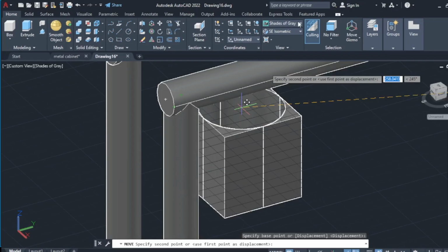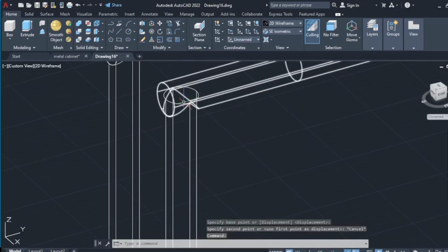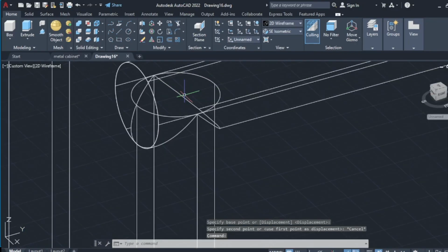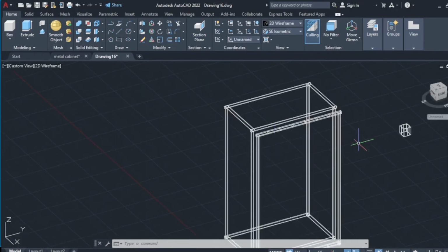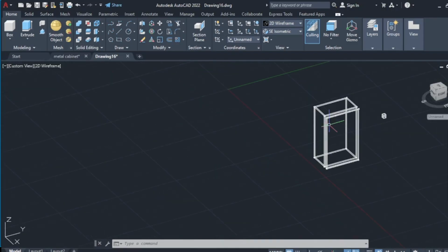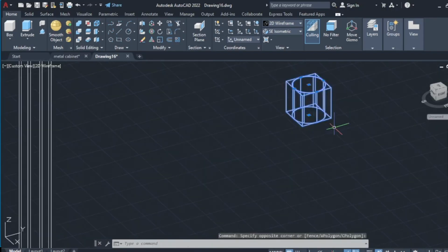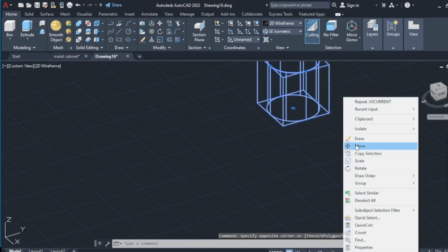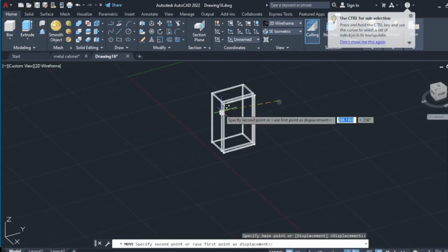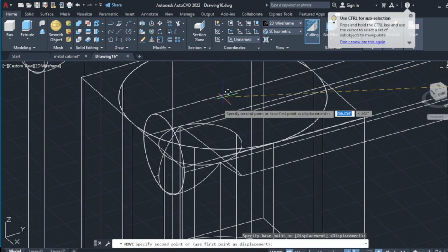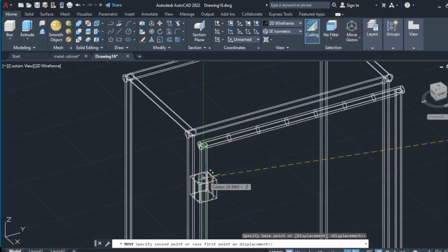So you guys can understand what I'm trying to do, we made a new circle here so that we can find the center of this rod, so we can drag this hinge to the center. That's exactly what I did. You highlight this, you copy or you move, you pick the center here, and you come here, you find the center here, then you just drag without doing anything.